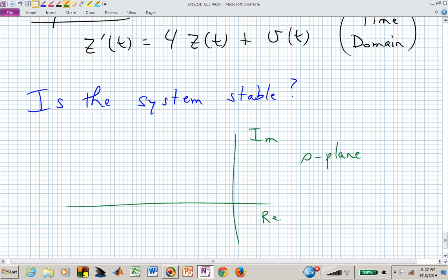If we're talking about the S-plane, and I now have sketched the S-plane, what are we typically thinking about when I say, oh, if you now have a system, and I'm concerned about its stability, now you want the poles, or these x's in your x's and O diagram, your pole and zero diagram, you want all of your x's to be in the left half plane. That will give you negative real parts. Yes?